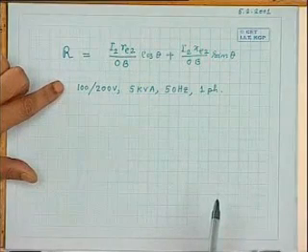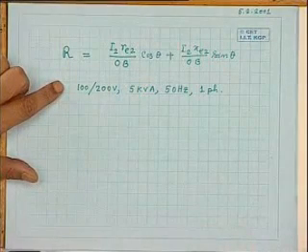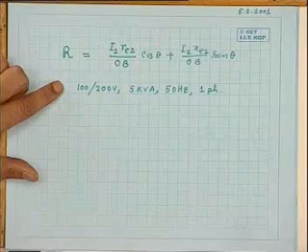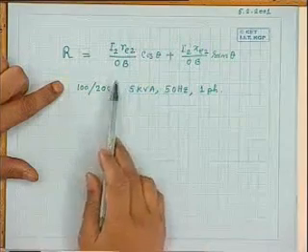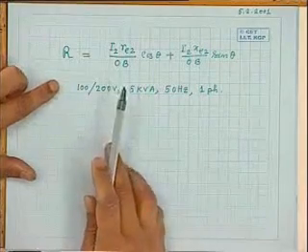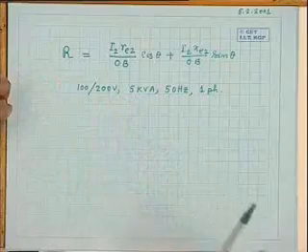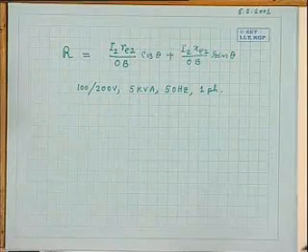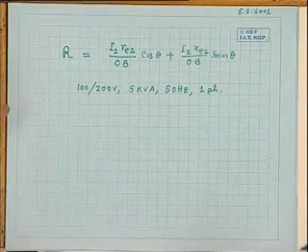Now the transformer is loaded by closing the switch. That terminal voltage magnitude will no longer remain 200 volt. It will change. So what is this OB then for this transformer? 200. That is under no load condition. Suppose after loading, it will become 198 volt, 195 volt instead of maintaining 200. Like that.